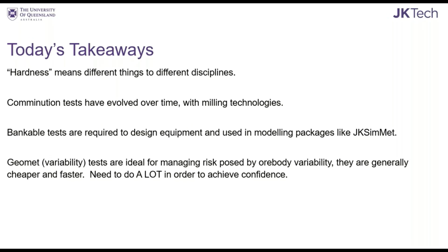Comminution tests have evolved over time, I guess very slowly. But ensure you choose the right test for the application you are considering. If you're doing design work, make sure you use bankable tests. And if you're assessing the variability side of things, look towards some of these Geomet style tests. Remember, they are cheaper, but you need to do quite a lot of them in order to get some decent confidence out of it all.